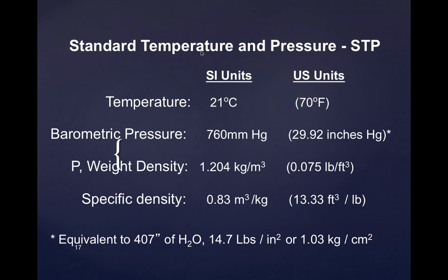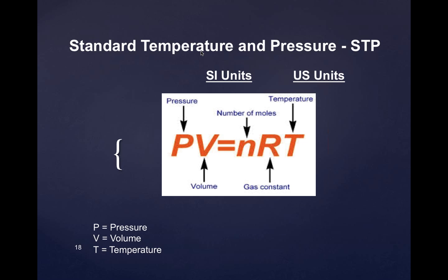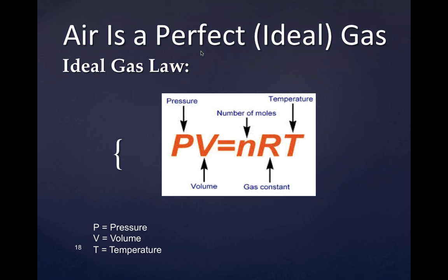Canopy hoods. Where do you use a canopy hood? What kind of situation? Well, you want to use it where the contaminant is going to go up into the hood. And where's that going to happen mostly? When you have a heated tank, right?